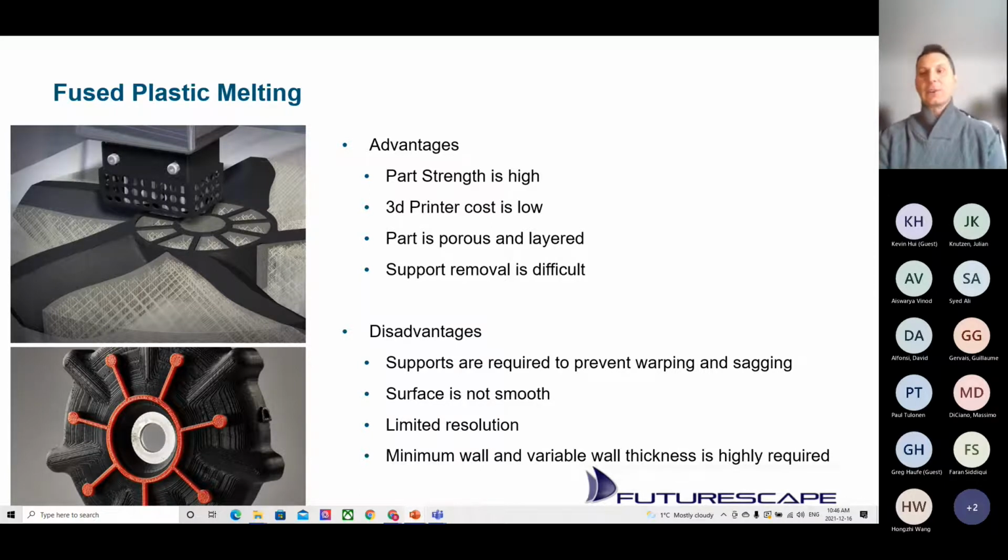If you need, for example, a part that needs to be sealed, or it's going in a liquid bath, or underwater, or you need it to be airtight, that can be limiting. You can do post finishing, like epoxy dips or putting it in acetone for smoothing, which I've done. But sometimes you have to do some post processing because of the porosity.